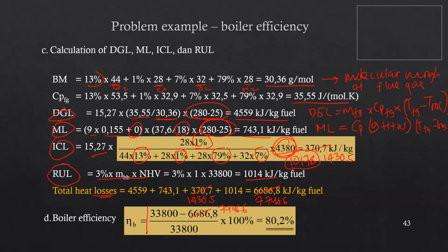33,800 minus 7.6 divided by 77%. So it's slightly reduced, because the losses actually increase when we use the proper units of the combustion heat of the CO for the incomplete combustion losses. So we have 77.1%. Okay, any questions for this problem?